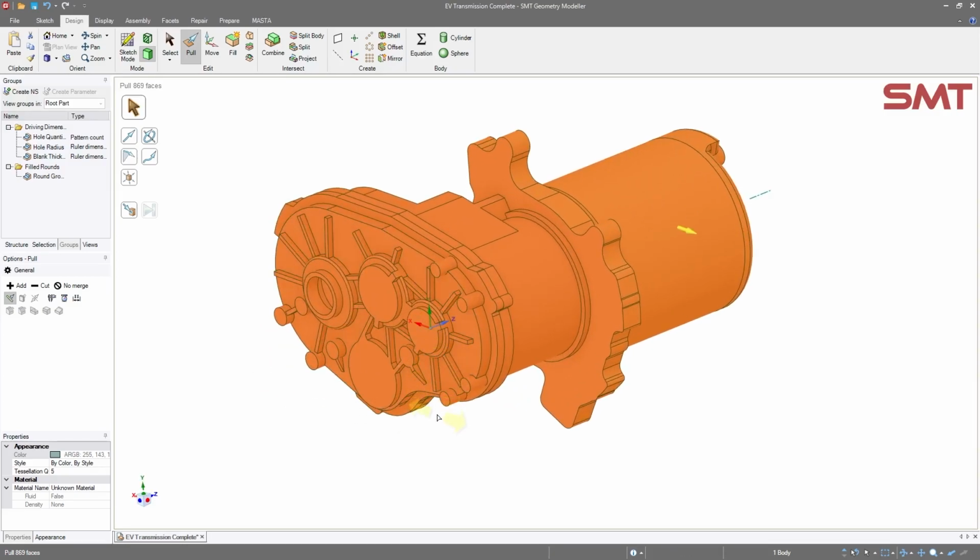A lot of the problems, even those that we saw in that last example, might be to do with trying to get the mesh to generate properly and to be the quality that you want it to be. And this is applicable across all meshing platforms, more or less. So I've shown you one way of doing this defeaturing. So that was with the prepare and repair tools and just modifying the geometry.